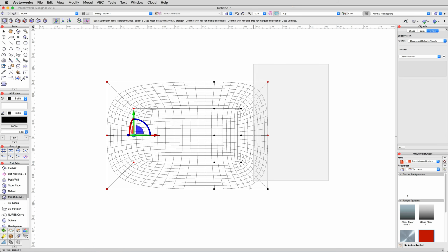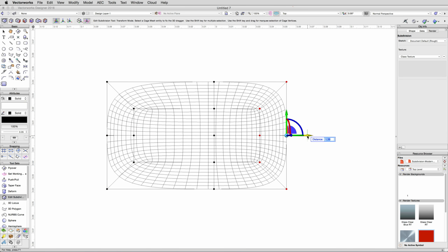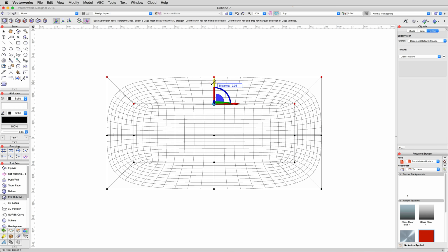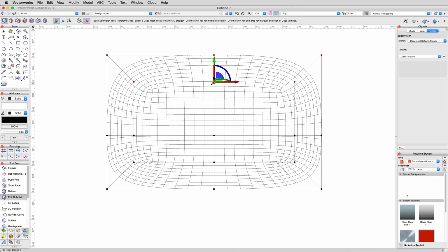We'll then do the same to the 6 vertices on the right, selecting them with a marquee, then clicking the red linear handle, but this time moving to the right, and entering a value of 4 meters, not -4 meters, to move these vertices to the right the same distance. Now, select the top 6 vertices as shown, and move them upwards 2 meters, using the same method we did for the left and right sides. And finally, select the bottom 6, and move them down -2 meters as well.